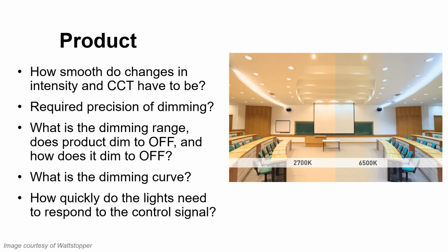What's the dimming range? The minimum level of stable dimmed output varies across different products, with dimming that drops to 1% and lower output typically being more costly. Applications like restaurants, theaters, and the like often require a very low dim level of 1% or lower, while spaces such as offices and classrooms might accept a higher dim level, such as 5 to 10%.